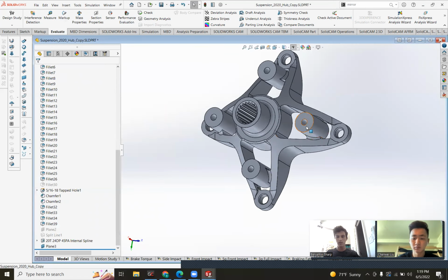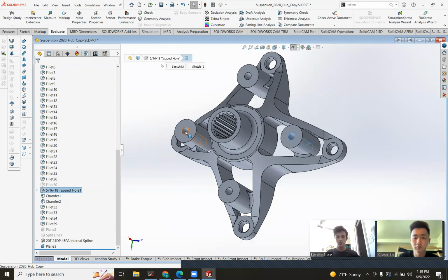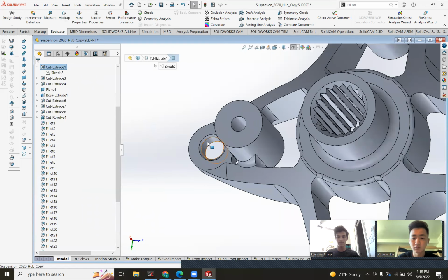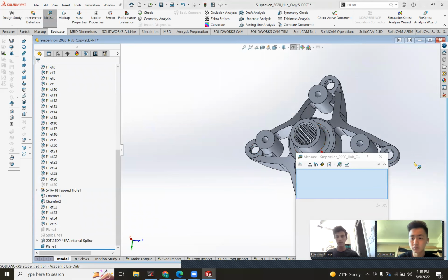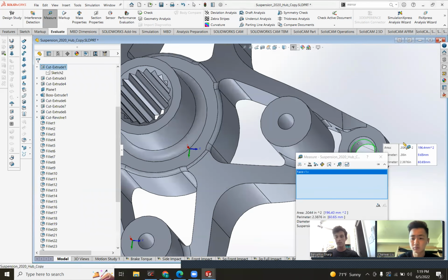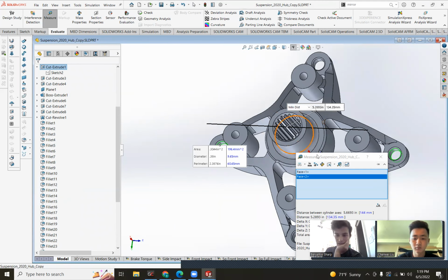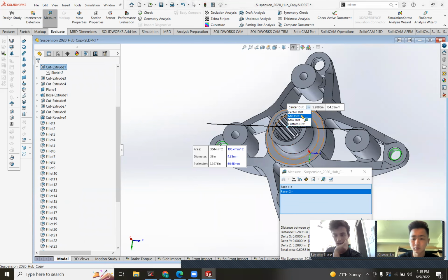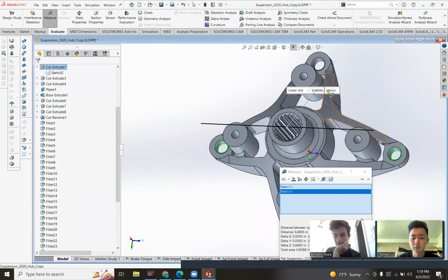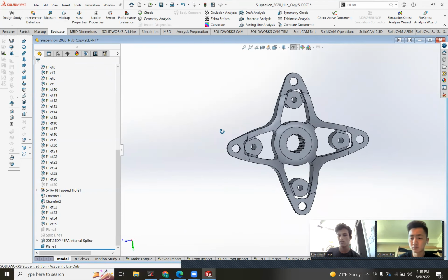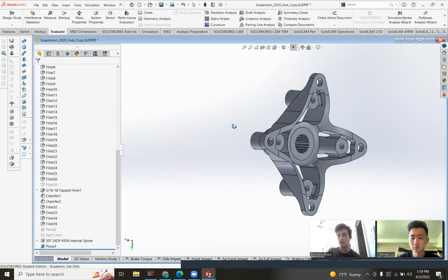The distance between these rotor mounting points has to match the rotor. And this diameter from here to here has to match our rims, which are and have always been 144 millimeters. But that doesn't mean you can't change the rims if you want to. It's just what they've been in the past and what we have on hand. The rest, I believe you can do whatever you want.